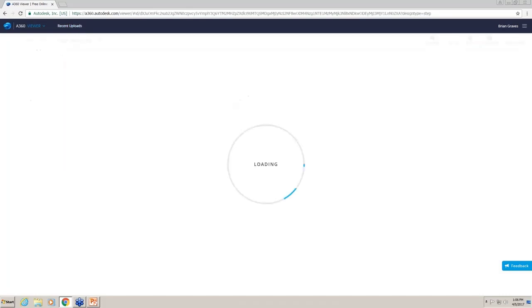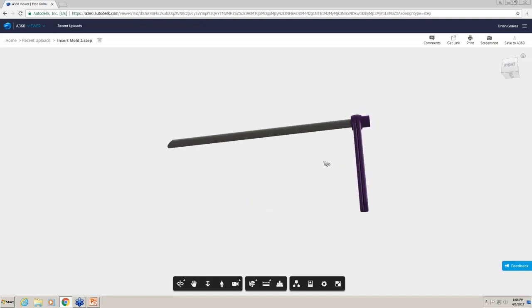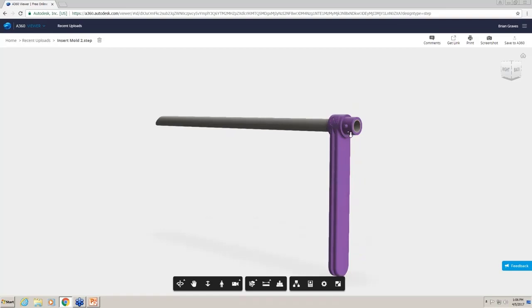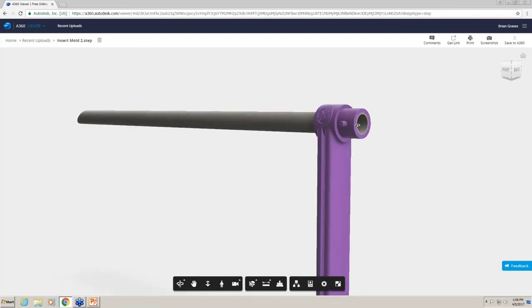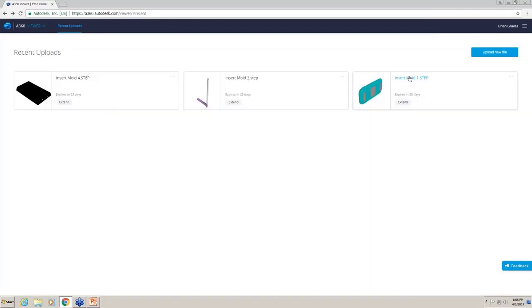All right, we'll get into the second one. Now this is a custom molded insert. This right here is a cannula tube. It's a medical grade or medical based product. We did the molding right here on this purple portion. This is a very custom part that's designed just like any other part. It's not your standard insert. We have some fine shutoff right here on the tube to make sure that no plastic moves into the cylinder portion of this, and you have another fine shutoff on this side. So, a fairly standard custom insert molded part.